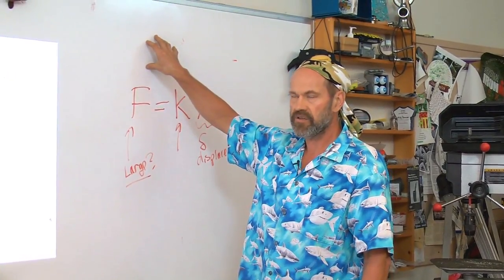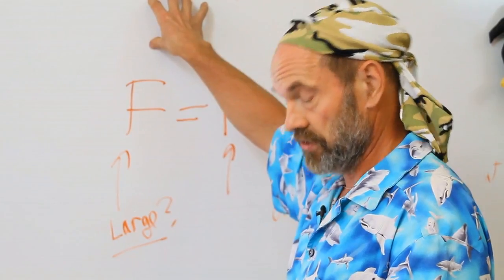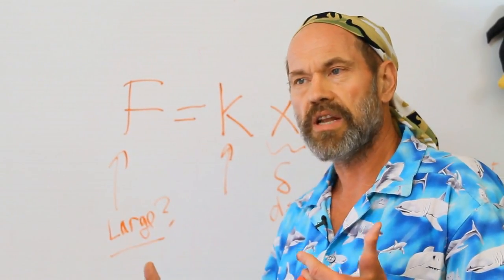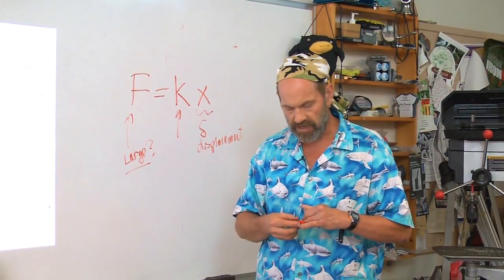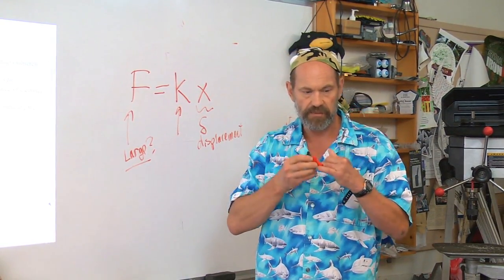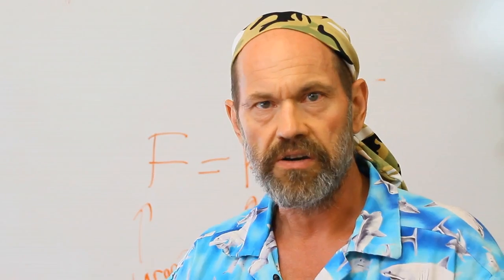Remember, the stress goes like the force to the 1/3. The deflection goes like the force to the 2/3 power. Learn how to use especially the nonlinear relationships so you can combine all kinds of simple machine elements into really neat, cool structures yourself. That's the art of machine design.